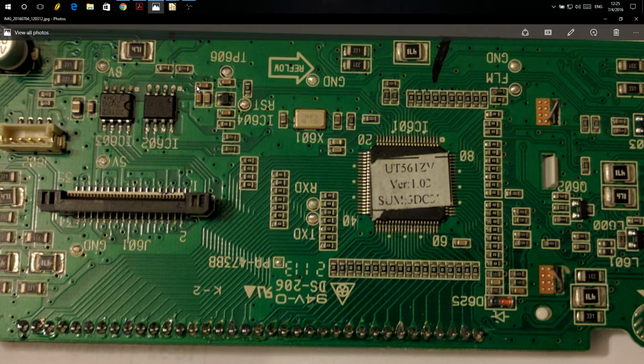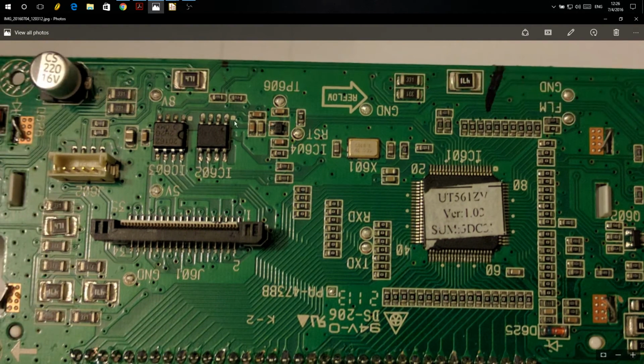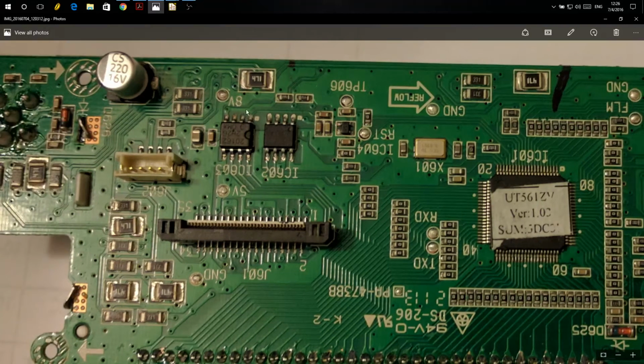But when it goes crazy, it writes just gibberish into it. I'm not sure if that's a software bug or a countermeasure of some kind, but if you blank it, it's fine. It's bizarre. I believe it's probably more like a software bug, and that's why I was screwing around on the data bus. This is using a 2-wire, and the DAC is using a serial, like SPI. And these are 2 different buses.